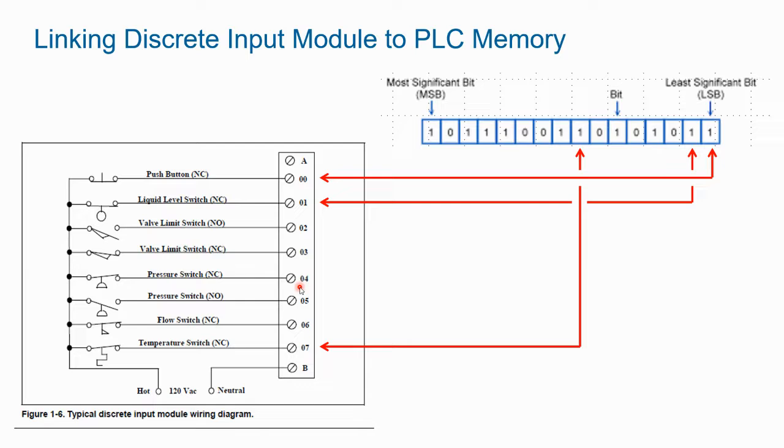Typically in the PLC world, especially the larger PLCs where they're modular and you buy the input cards separately, not the Micro Nanos, which are embedded with IO and have some odd numbers to them, but if you're buying a card from, like, ControlLogix, they're always going to be based on powers of 2 as far as the number of points on the card. There'll be an 8-point card, a 16-point card, and the largest they make would be a 32-point card. Those are all powers of 2, and they're all very significant based on some of the properties of the binary number we were just talking about.